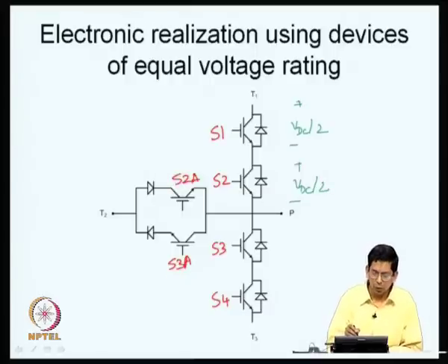So, let us say you take the switch S1 and S2. Now, S1 has a role, one is to connect the throw T1 to this terminal here. The other function it has is to open, to serve as an open connection between these two terminals now. Now, let us say if you want to connect pole P to throw T1, both of them have to be on. If you want to disconnect pole P and throw T1, it is not necessary that both of them need to be on. It is enough if S1 alone is off and S2 could still be on, right. Only if both the switches are on, it could be conducting now. So, there is some redundancy here.